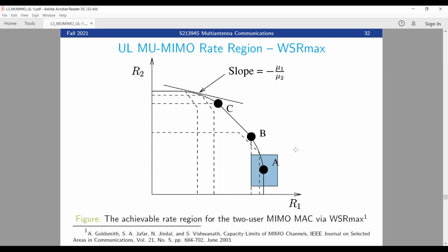What is the transmit strategy? If user 2 is not there at all, right? Point to point MIMO. What is the capacity optimal strategy? Point to point MIMO, right? SVD, right? What is the covariance matrix? Single vectors, water filling. What is the X? H1 is, assuming H1